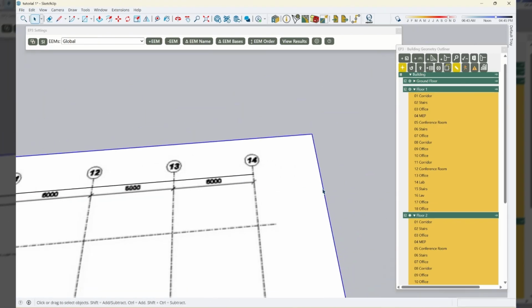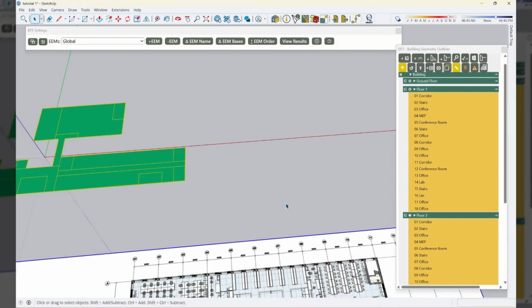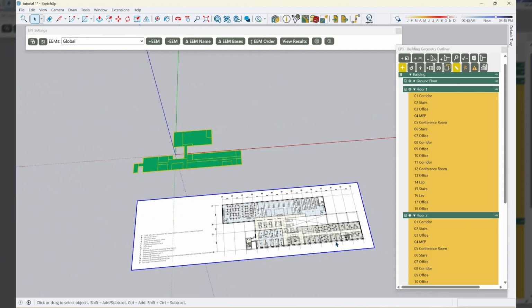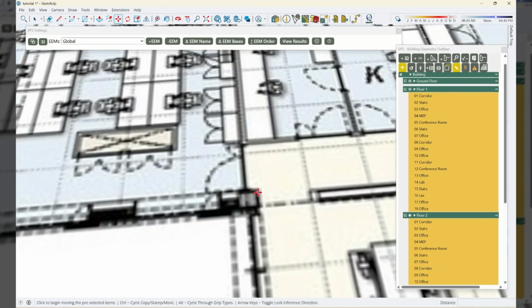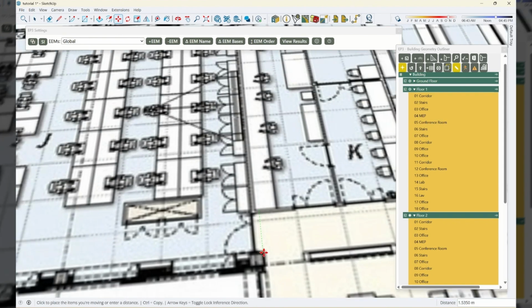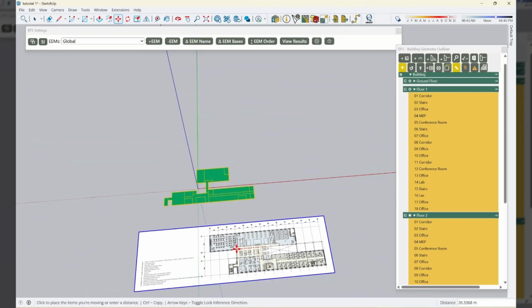Space bar to get select tool. I'll select both and then hit 78 meters. Now, before I assign it to the second floor, I can actually position it first. So I'll grab this corner again. This is our nice reference corner.